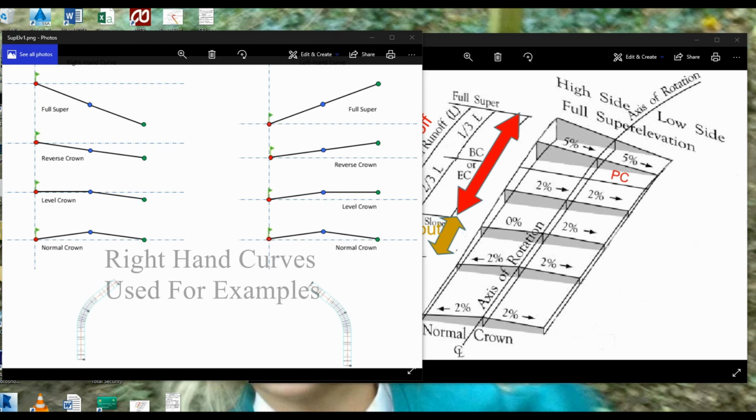Superelevation is designed to ease vehicles into, around, and out of a curved stretch of road whilst travelling at speed safely. This is achieved on approach to the curve by gently lifting one side of the road, the outer edge, in this case pivoting upwards from the centreline axis. This is done until the outside edge is at the same slope percent as the inside edge from the crown. This is called continuous cross slope or continuous crown. From this point on, the whole road, that's both sides, will pivot or turn on the centre line upwards until maximum super elevation is achieved.